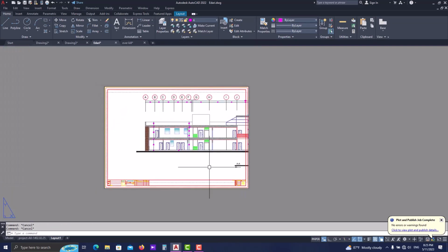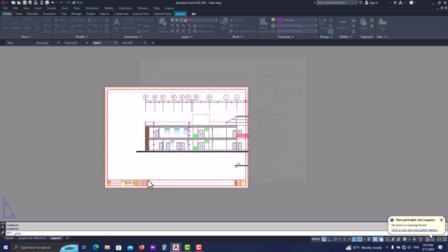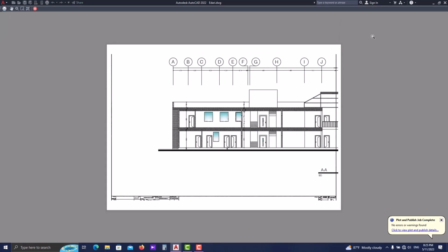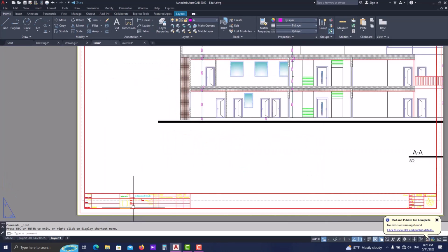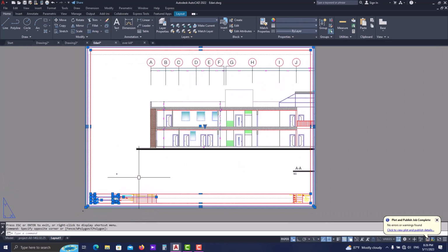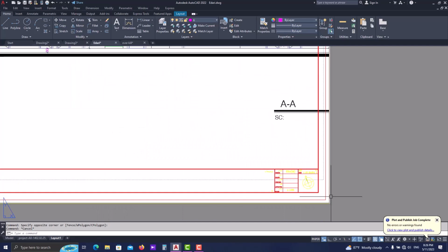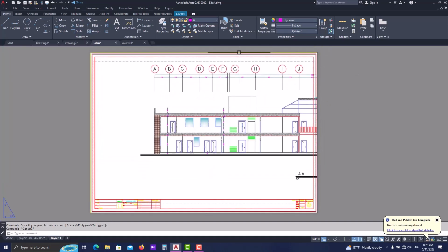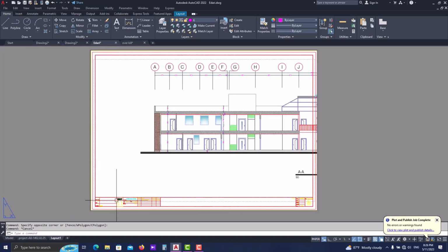Now, if we go ahead and check the preview of this output of this sheet, here we go, and you can continue creating separate sheets after this as well. And by the way, don't forget this, guys. This is a very important point. Always try to specify an edge for your view when you set it inside your sheet. You can use offset, for example, like 2 cm, so that the printer would recognize it.